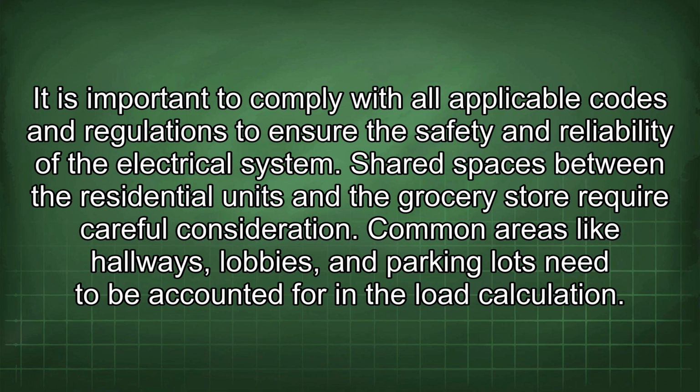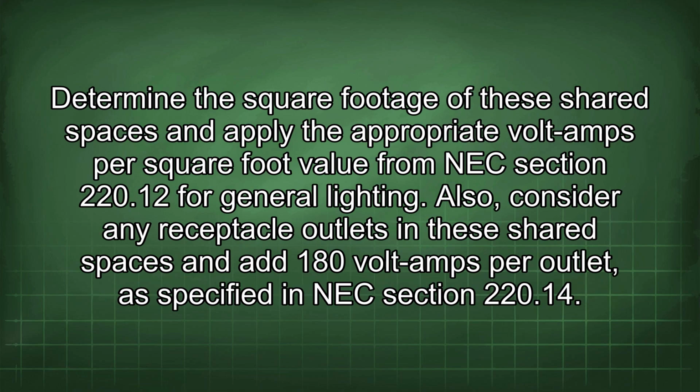Common areas like hallways, lobbies, and parking lots need to be accounted for in the load calculation. Determine the square footage of these shared spaces and apply the appropriate volt-amps per square foot value from NEC section 220.12 for general lighting. Also, consider any receptacle outlets in these shared spaces and add 180 volt-amps per outlet, as specified in NEC section 220.14.